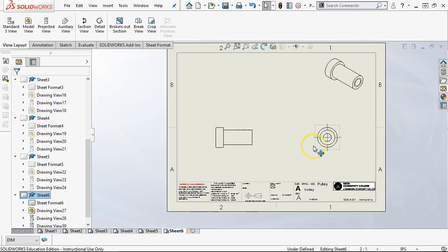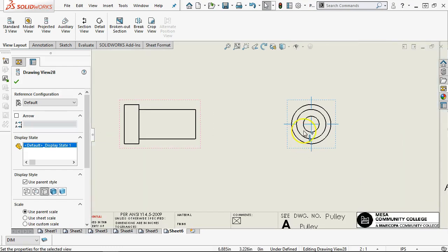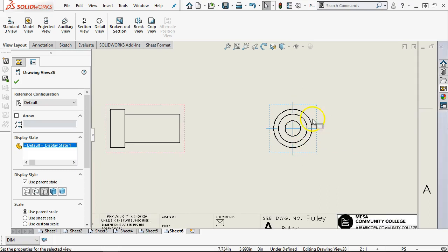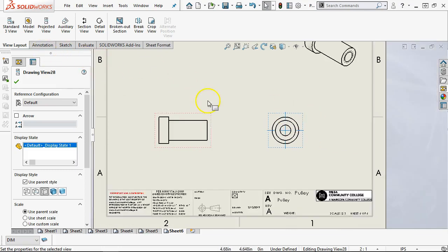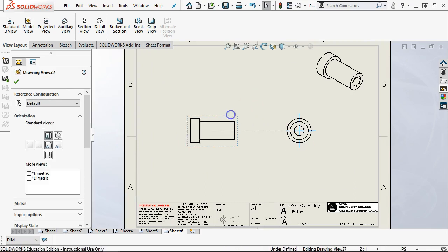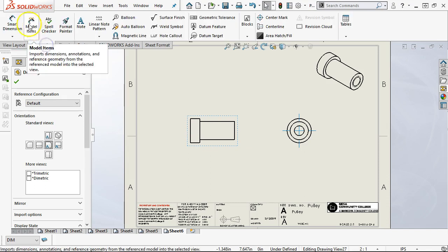And then since I saw the tapped hole here, but it's not really showing up here, so that's interesting. It didn't give me the dashed lines. So let's go through the same process. We're going to put our starter dimensions on it, and we designed for convenience, but for manufacturer, I probably want to pick a standard datum to work from.